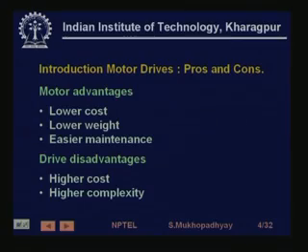The main disadvantage of adjustable speed induction motor drives is the fact that they require more complicated electronics. So the inverter and its control circuitry are more complicated and therefore more expensive, but cost is a very changing factor. As time is passing, the drive cost is coming down. So induction motor drives have really become a viable alternative to DC motor drives and are replacing DC motor drives in various industrial situations, especially highly rated ones where the power rating is high. So having said that,